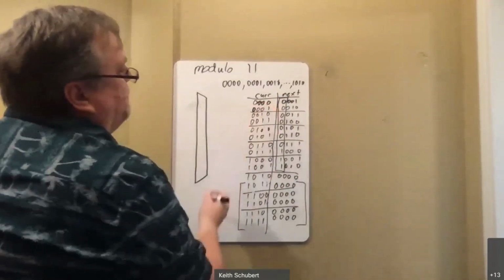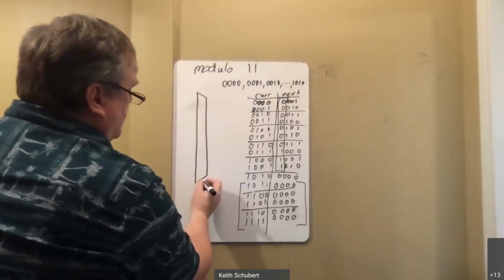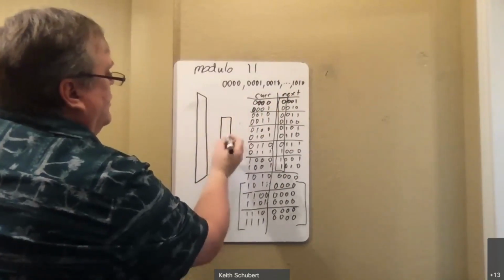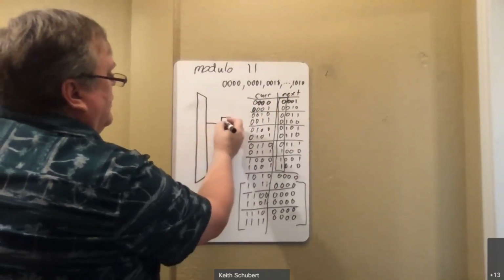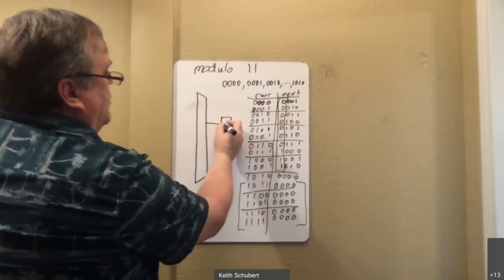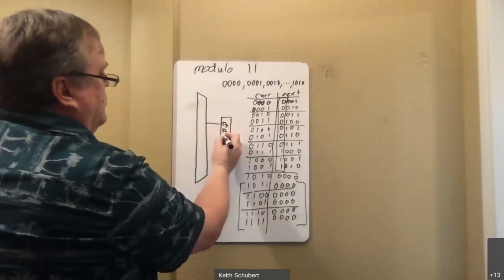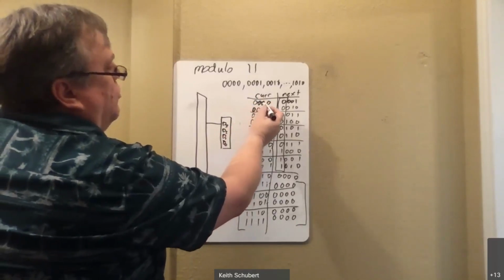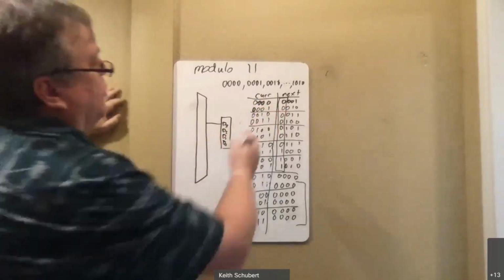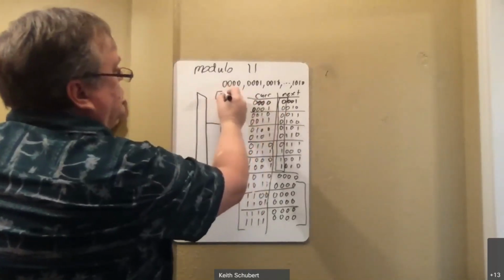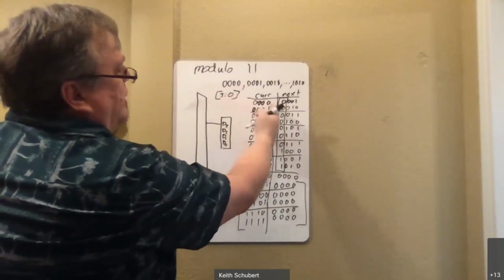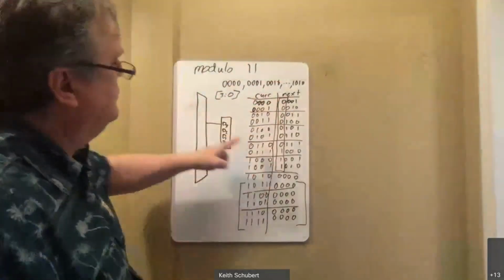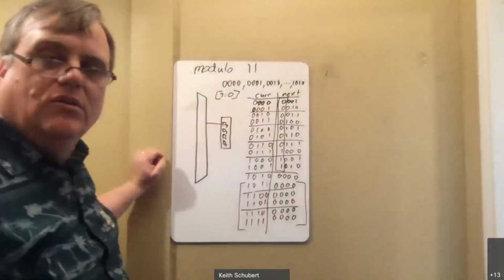Mux design says you take the first 3. So that's my current states. I've got a 4-bit parallel load: D3, D2, D1, D0. Because this is 3, 2, 1, and 0 in my positioning. So if we were to implement this in Verilog, you would just go 3 down to 0. This is 3, that one is 0, bit naming wise. I'm going to do the first column, current to next. So I'm doing the one that's going to do D3. Does that make sense?